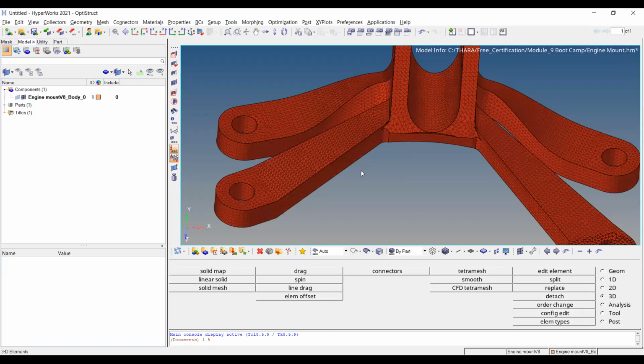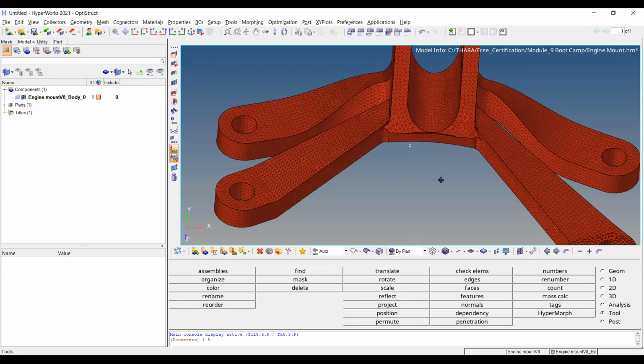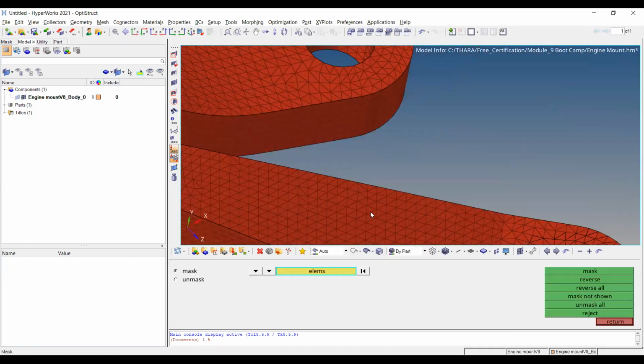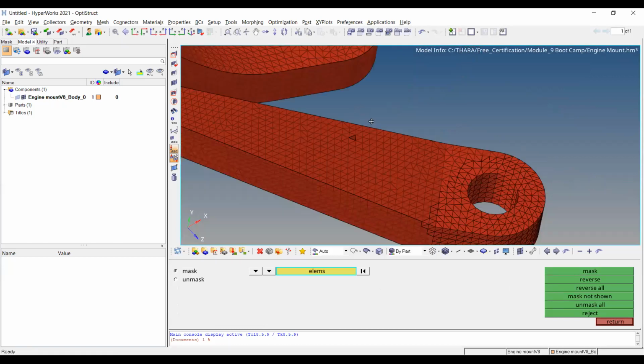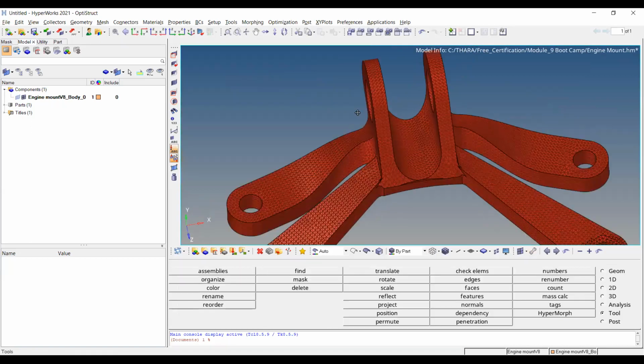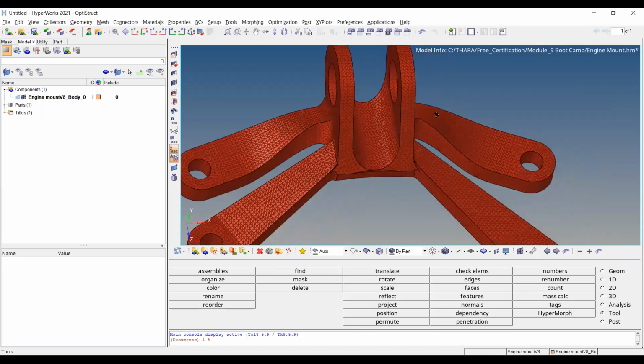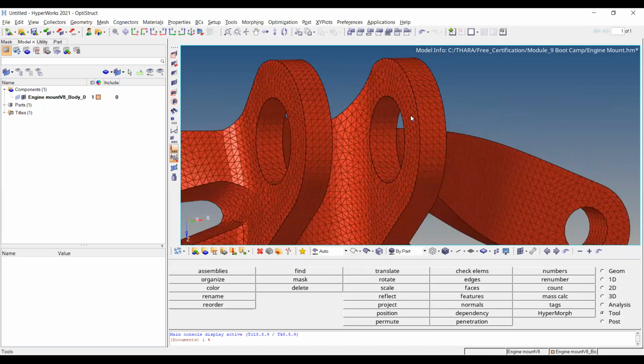Now, the other important check for the 3D element is 3D faces. As I said, I'm just extracting the 2D faces. See, since this component has 3D elements, I now want the 2D elements for this one. As soon as you finish your 3D model, what the CAE industry follows is that we require 2D faces along with the 3D elements also. I have only 3D elements now, so I need 2D elements also. How to create the 2D elements using 3D?